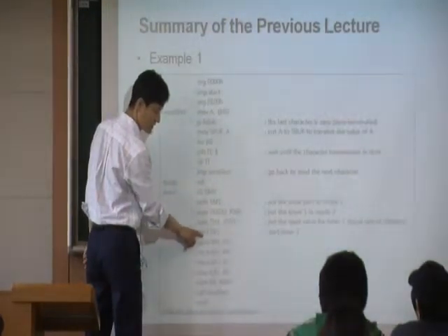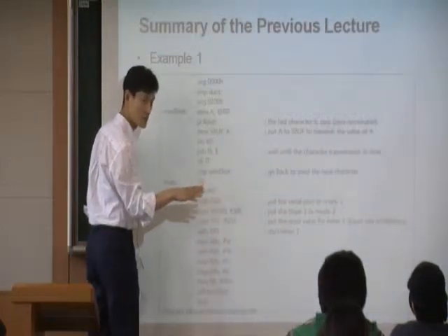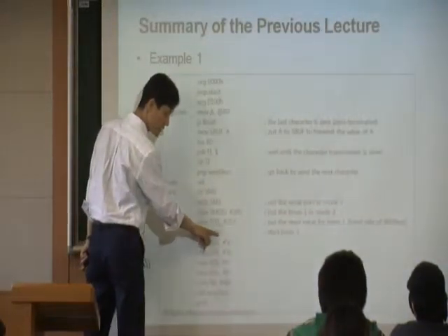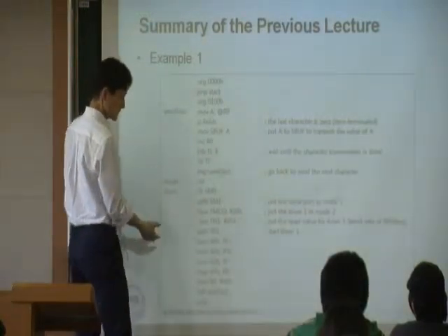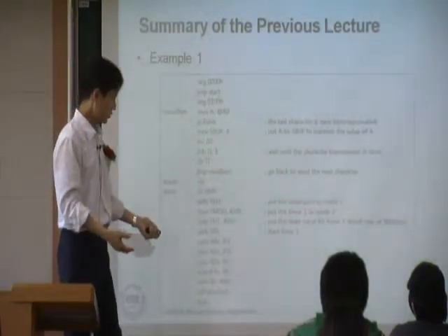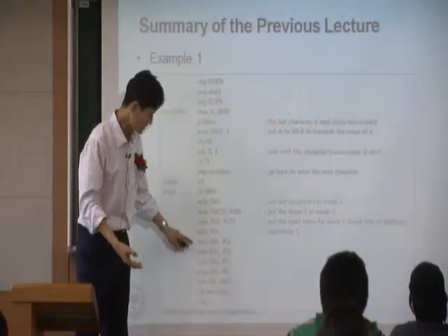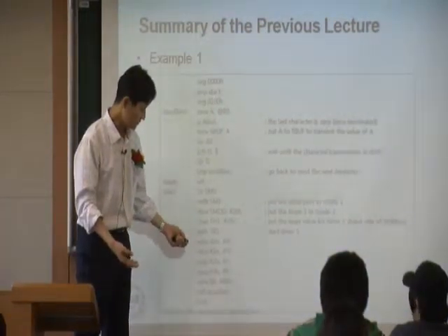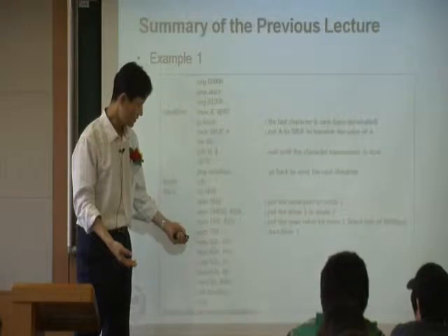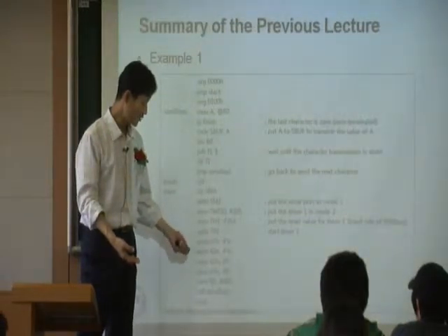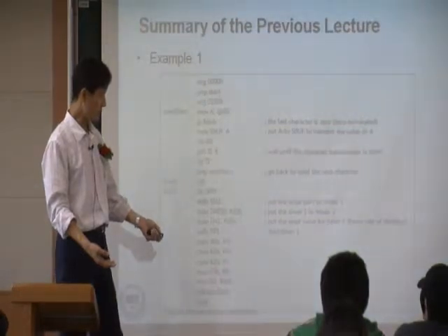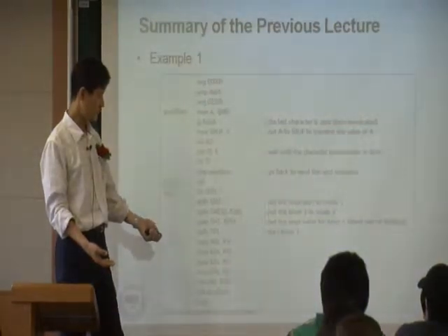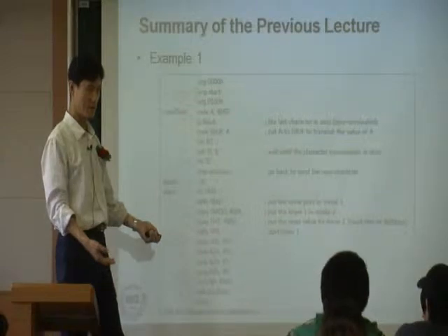And the next line, set B TR1, runs the timer. Once you execute this line, your timer is running. Then in the next lines I copy A, B, C, and 0 into memory 40H to 43H.